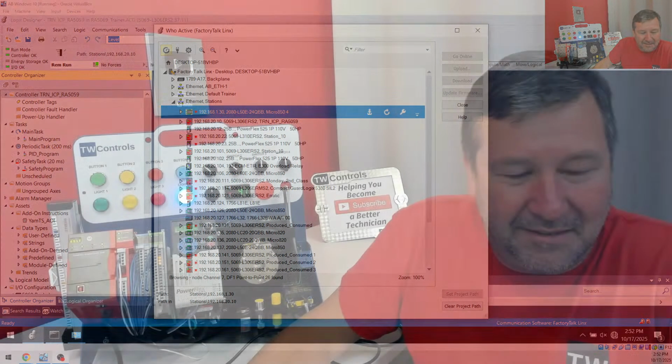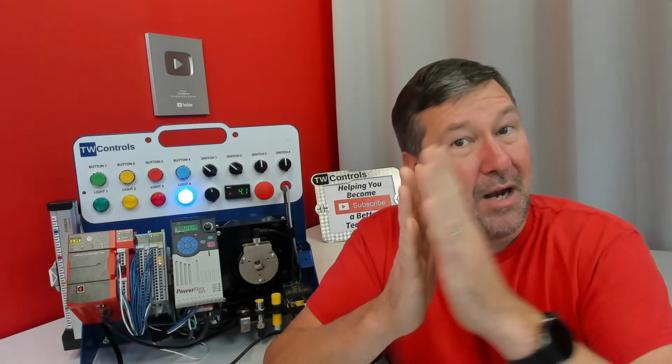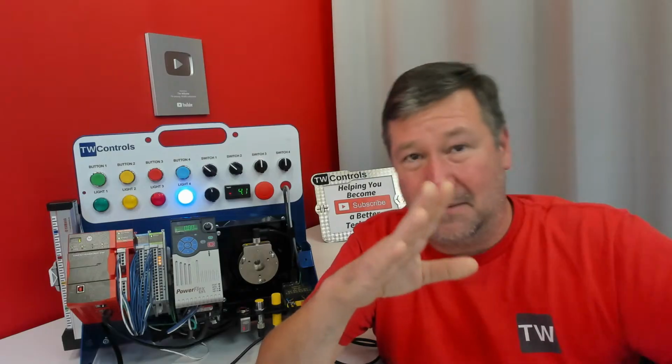Remember the ping. So if you don't see it there, ping the device. The ping is really the key one. No good ping, the problem's in your Windows configuration, or it could be the PLC's turned off. Good ping, that's when we go into our driver configuration.